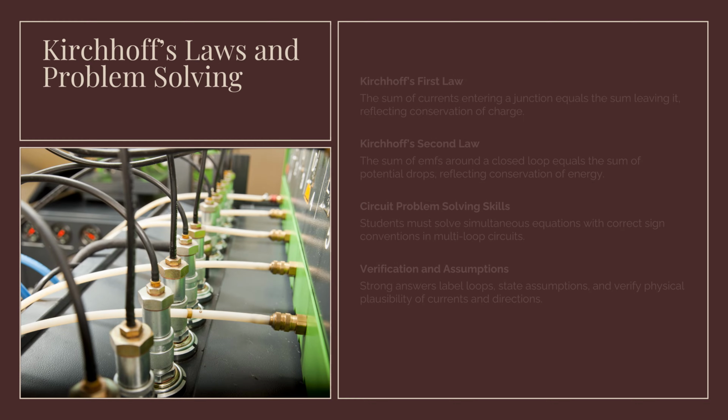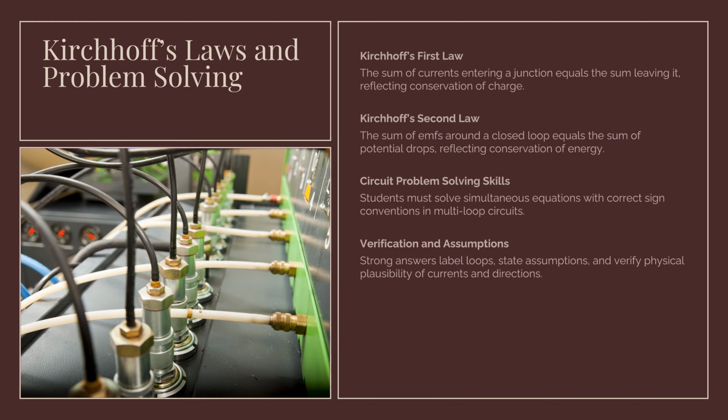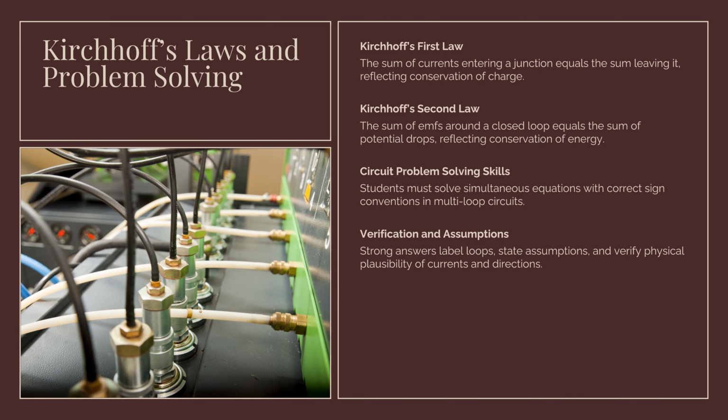Kirchhoff's laws provide a systematic framework for analyzing complex DC circuits and are rooted in fundamental conservation principles. Kirchhoff's first law states that the sum of currents entering a junction equals the sum leaving it, reflecting conservation of charge. The second law states that the sum of EMFs around a closed loop equals the sum of potential drops,